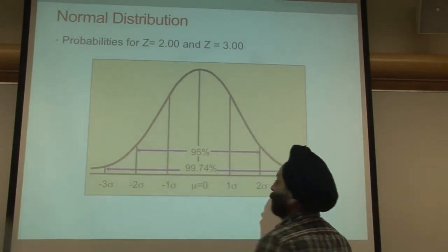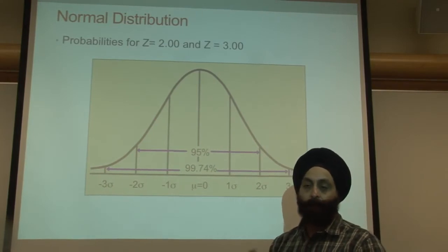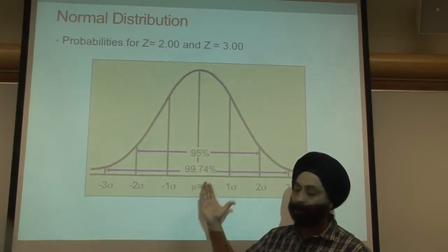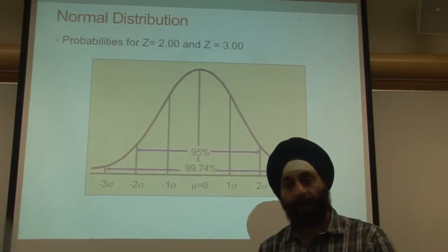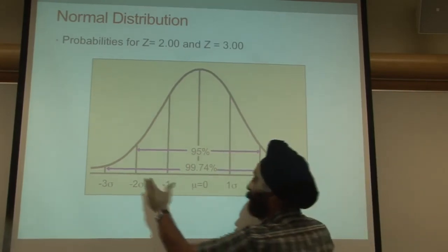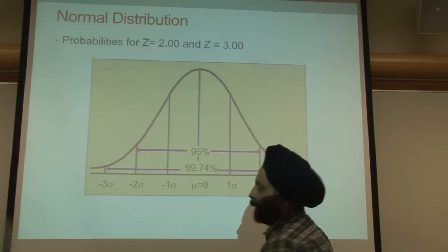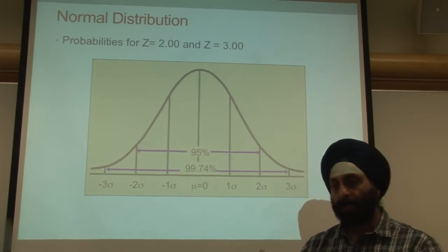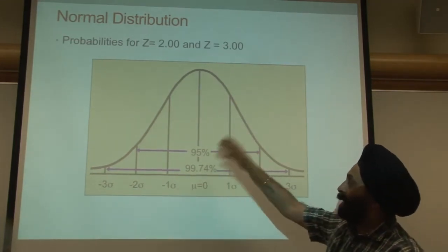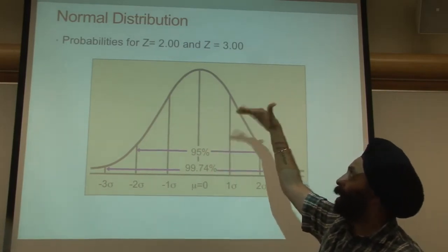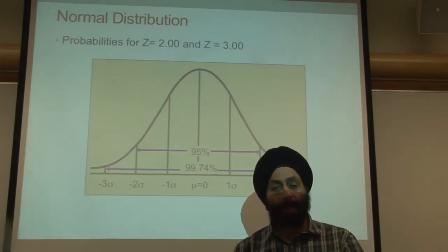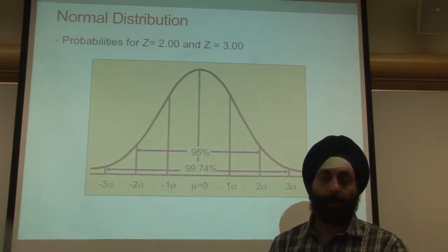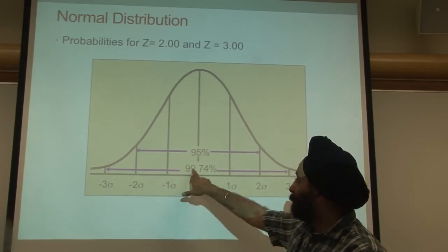normal range. So typically, unless otherwise specified, most of the time in industry, it's always the plus or minus 3 standard deviation that is used, which is 99.74%, which is virtually everything in here is normal, and that is what you're trying to capture. So whenever you hear, z value of 3 is the standard, the default value, and unless otherwise specified, that's what you'll be using. And sometimes they may say calculate 2 sigma. In that case, you'll put z of 2. But otherwise, typically in industry, you always end up calculating 3 sigma control limits, which is a z value of 3.